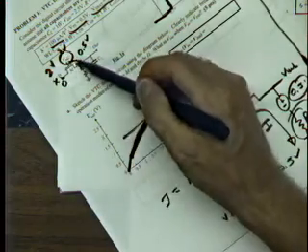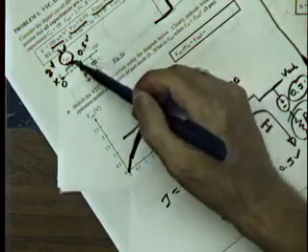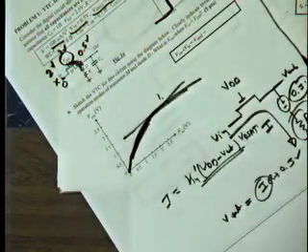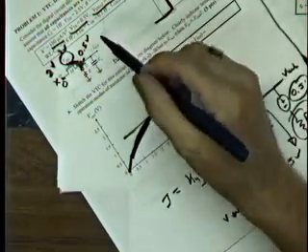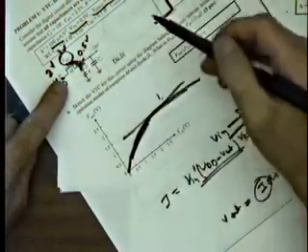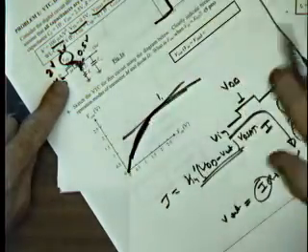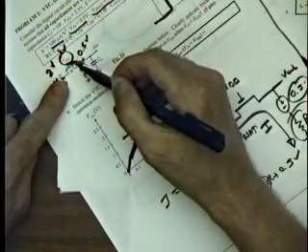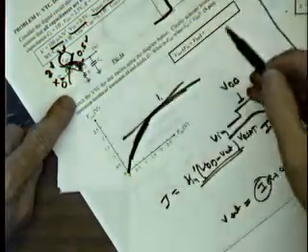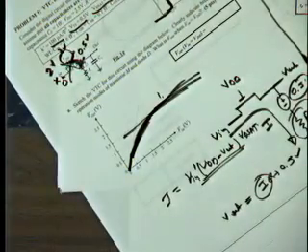The VGS is right here. The source is the lowest voltage of the transistor. So the VGS actually, that's why the transistor is going to shut off. Once the output gets to 1.5 volt, the VGS is going to drop below VT. The NMOS device shuts off, and we basically get a flat type of response.